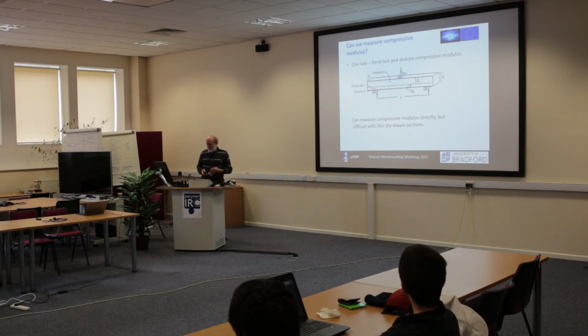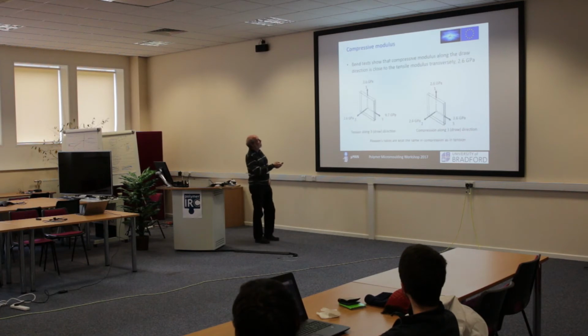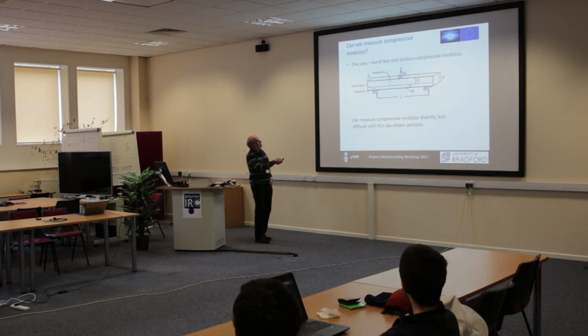Can we find a compressive modulus? You've got these thin strips of material, less than a millimetre thick, half a millimetre, a third of a millimetre. Compressing them end to end to measure the compressive modulus directly is going to be a bit awkward. So we haven't done that yet. But what we have done is to do bend tests. And of course, with a bend test, you've got compressive zones and tensile zones.